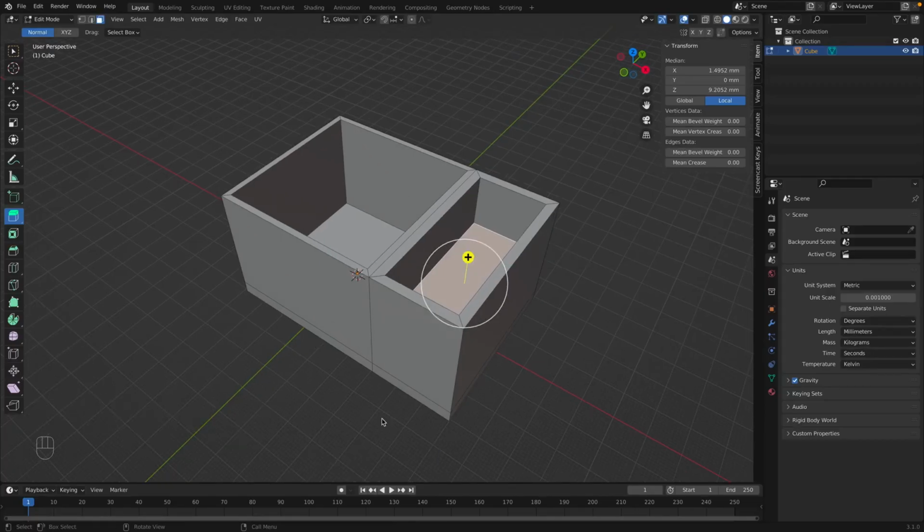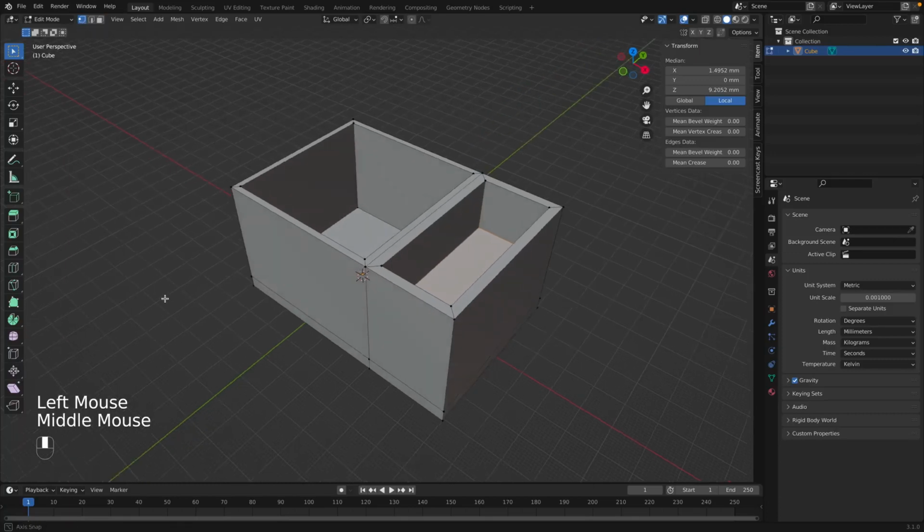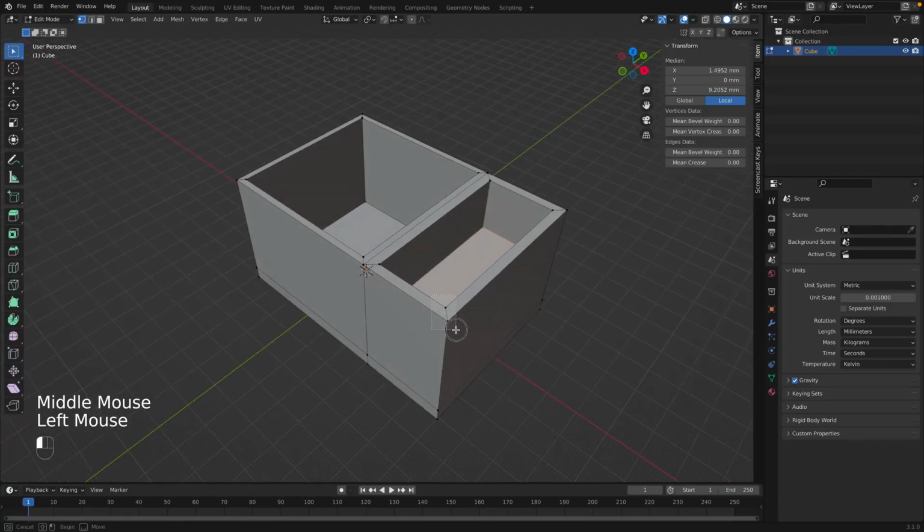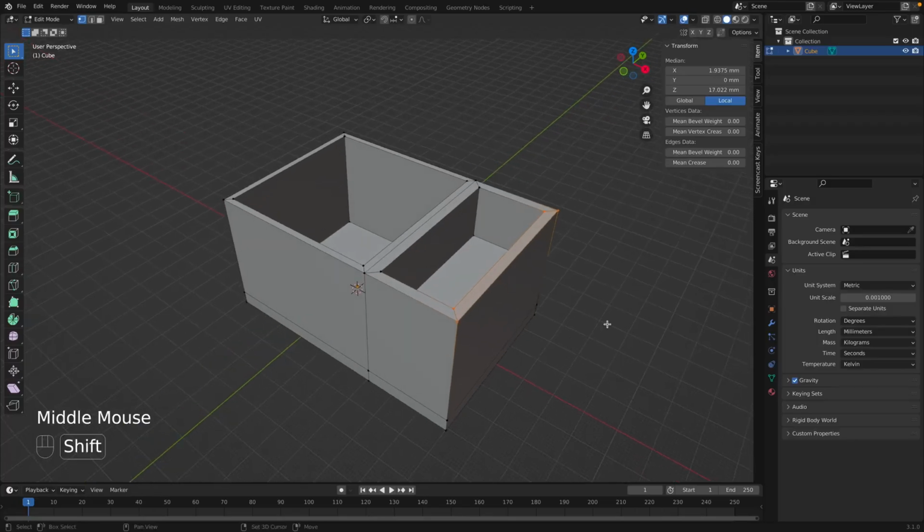So now let's say we want to modify it a little bit more. Let's go back to the regular selection tool, and let's go to the point selection: point, vertex, or node. I'll use all three of those interchangeably. Officially, it's the vertex selection mode. And now we can select these points here by clicking and dragging. If you hold Shift, we can select these other 2 points. Now we have all 4 points selected.